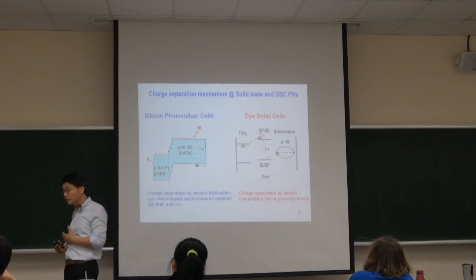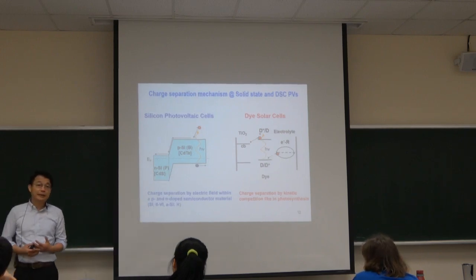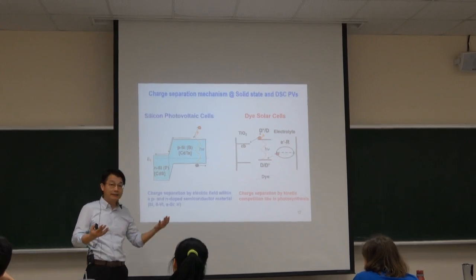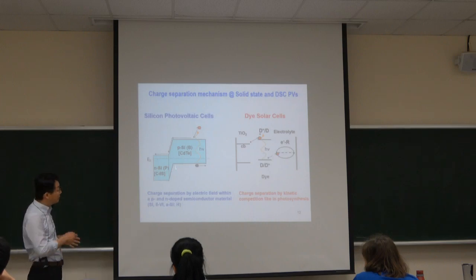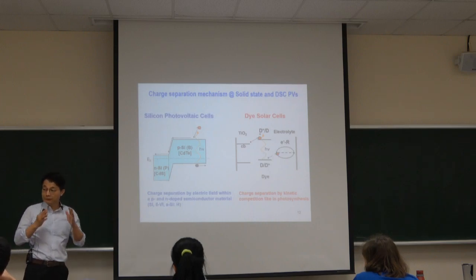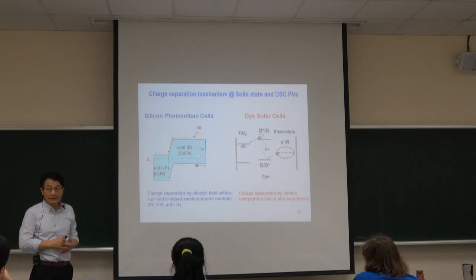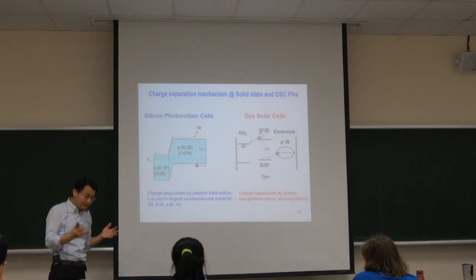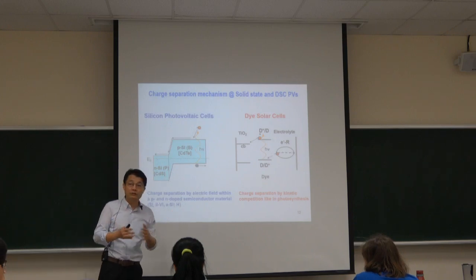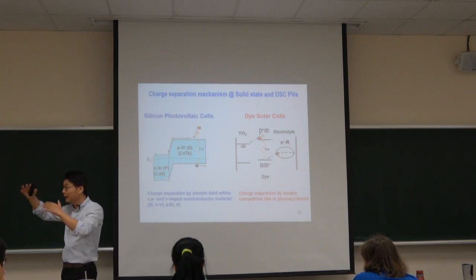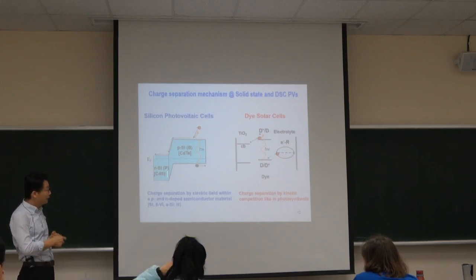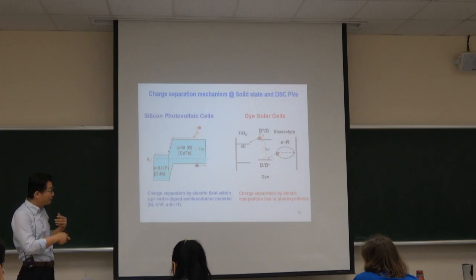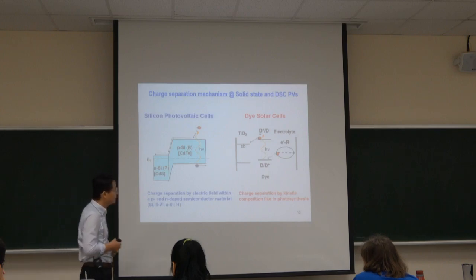And then you have to go through a purification process to get 6N purity, and even higher. Then you have the p-type silicon substrate, and you have to deposit n-type silicon. Then you proceed with something like a texture structure to create a high surface to volume ratio, in order to get a high absorption surface on the silicon surface.